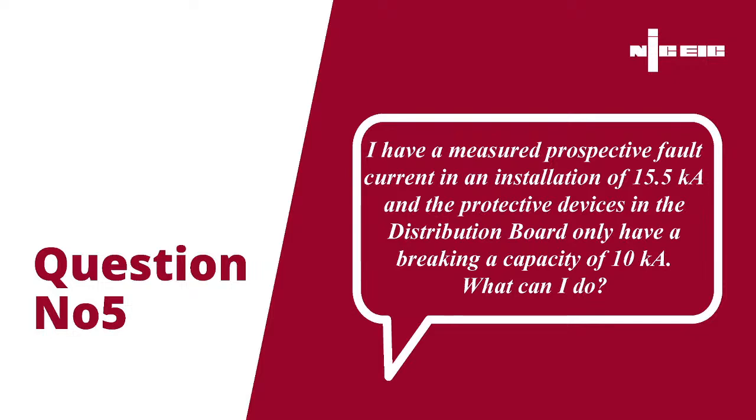Okay, another good one that was a bit of a light bulb moment for me when I was first introduced to this concept. So a contractor had a measured prospective fault current in an installation of 15.5 kA, and the protective device in the distribution board only had a breaking capacity of 10 kA, and asked what could they do. And we pointed out to them this principle of backup protection.